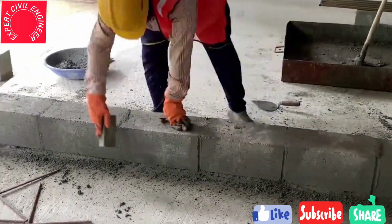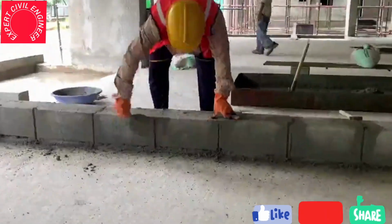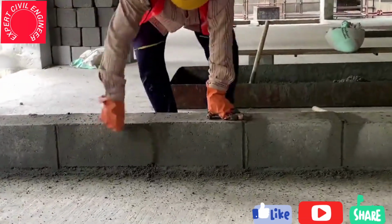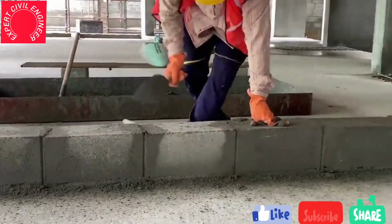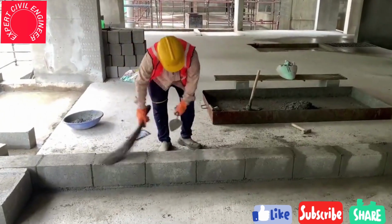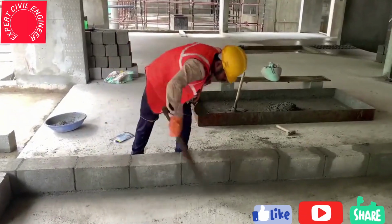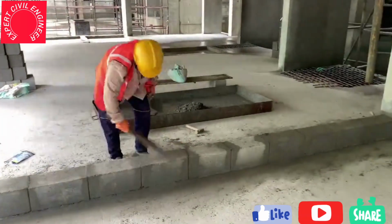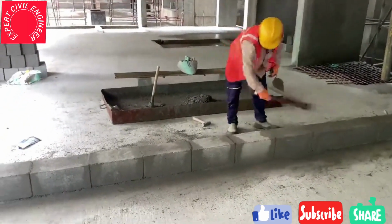Use the pointing trowel or aluminium straight edge to shape the mortar joint. Drag the trowel along the joint, creating a smooth and V-grooved pointing. Racking of joints: masonry face joints are raked out to a depth of about 10 mm. The removal of excess mortar should be carried out after completing the pointing process. Cleaning should be performed using a broomstick, ensuring that any excess mortar is thoroughly removed from all around the blockwork.